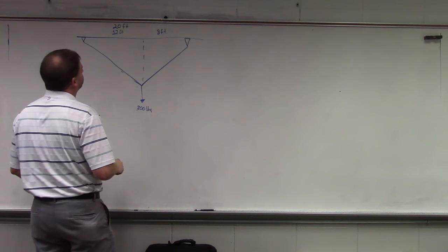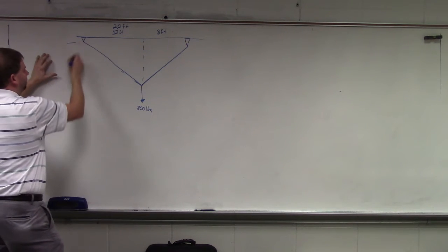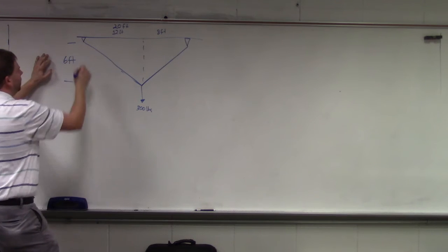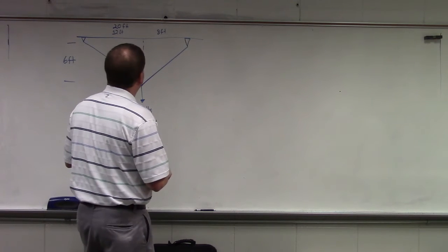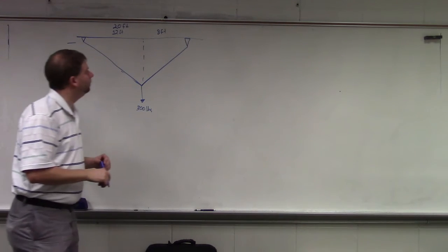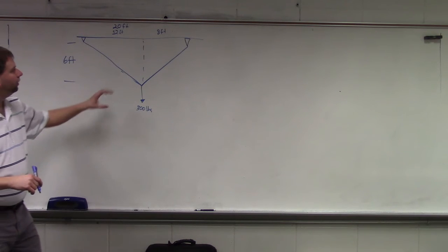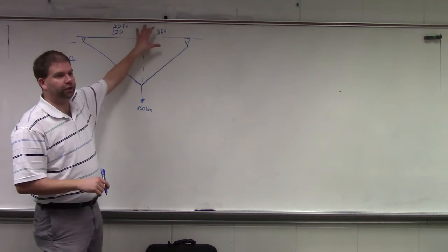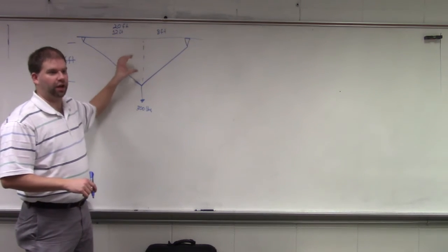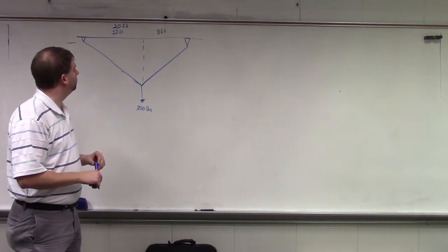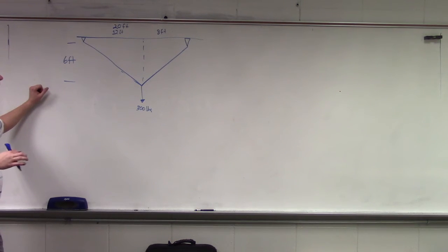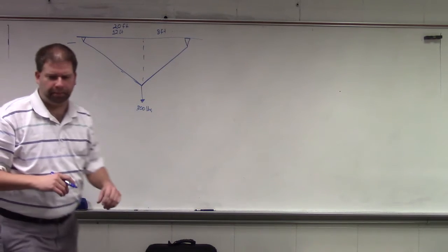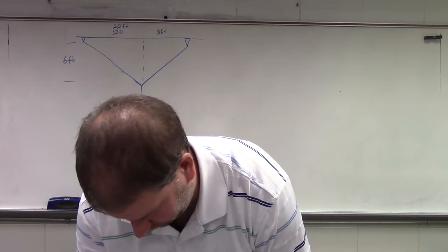Okay, what else does it tell us? What's this distance? 6 feet. Which question is this? BD. So this is B on page 17. B, okay, B as in boy. So if this is 6 feet and this is 8 feet, it's a 3, 4, 5 triangle, right? But it's not, because based on what Rush gave me for the answer, our angles aren't 30, 60, 90, they're different. Or no, maybe that's a 30, 60, 90, but it's on the force polygon, never mind.